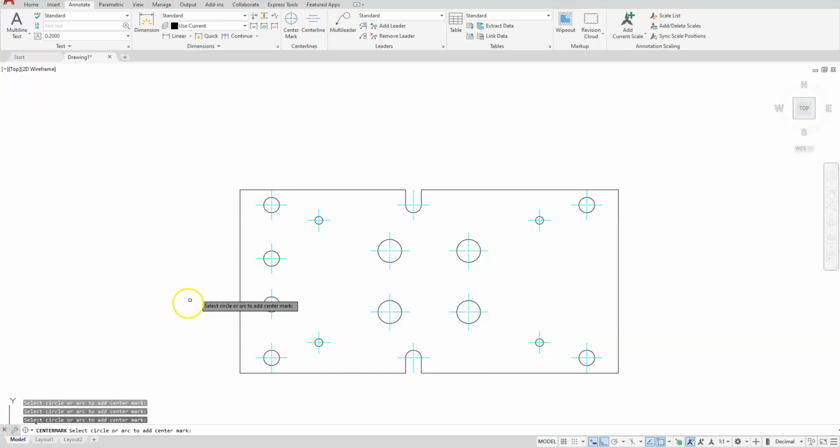Okay, and now we can use the center line command to connect the lines between the two. So if I use center line, I select this line and this line, you're going to see that AutoCAD will connect the line in between it. I'm just going to hit the enter button on my keyboard just to continue this, so I'll select this line to this one. And all I'm doing, remember, is just hitting the enter button to take me back to the last command. And I'll complete this cycle going all the way around it.